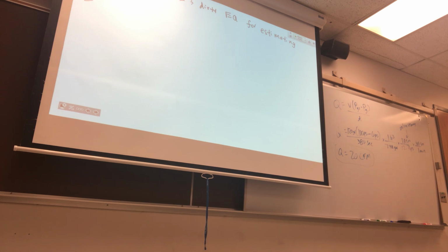So, our change in pressure, or our line loss, what pressure we're losing, that is the pressure 1 in absolute pressure. Okay, very key. This is our absolute pressure that we're using. And that term is squared, minus the second absolute pressure squared that we get.